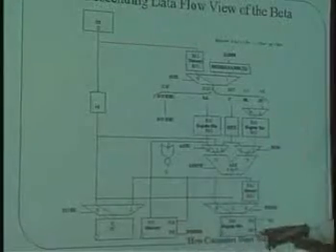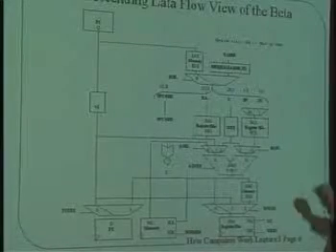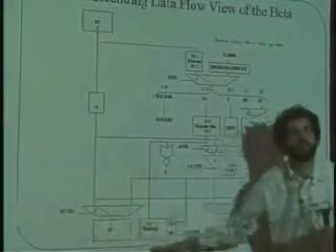In the same way, whether or not we're going to write into the register file will be determined by whether the WE here is high or low when this clock goes off. But the timing idea is that every instruction is transitioned from the present one to the next one by the clocks going off on the bottom line here.